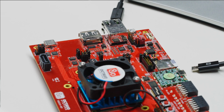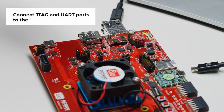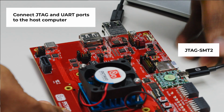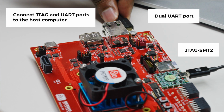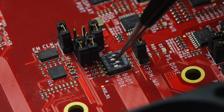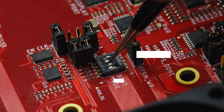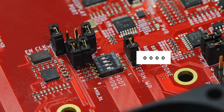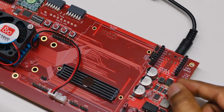To prepare the OSDZU3-REF development platform in JTAG mode, connect a micro USB to USB-A cable between the JTAG programming module on the OSDZU3 reference board and your host computer running Vitis. Select the boot mode to PS JTAG, that is 0000. Turn on the OSDZU3-REF development platform by flipping the power switch.